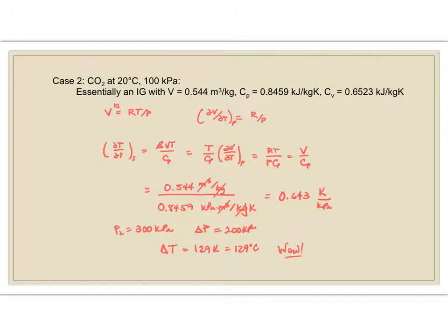And so that's why when we compress gases, we don't compress them to very high pressures all in one jump, and then we usually do some cooling of the gas before we would compress it in the next stage.